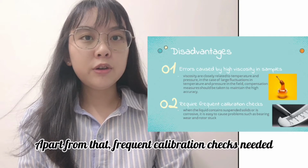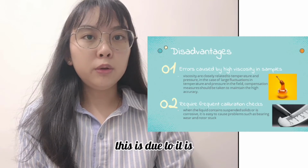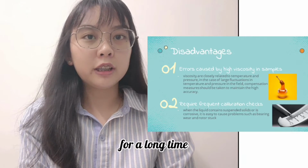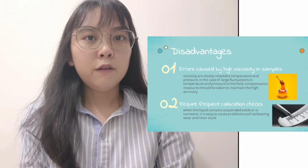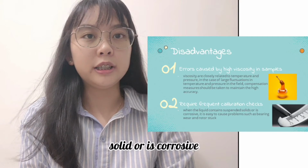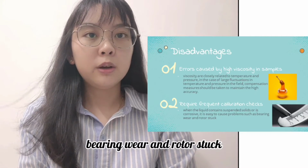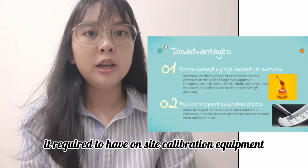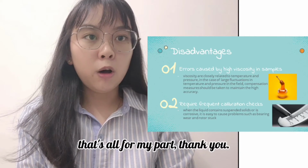Apart from that, frequent calibration checks are needed for turbine flow meters. This is because it is difficult to maintain the calibration characteristic for a long time, and it is necessary to periodically recalibrate. For non-lubricating liquids, when the liquids contain suspended solids or are corrosive, it is easy to cause problems such as bearing wear and rotor stuck. When high accuracy is needed, it requires on-site calibration equipment that can be used regularly to maintain its accuracy.